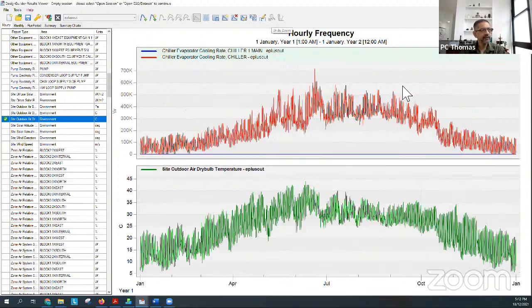So what I can do is take that 700 and split it into a 40-60 ratio. So about 250, 280 kilowatts and 420. So what I'll do is make both slightly bigger than that, make them 240 and 500. Okay, let's say 250 and 500 kilowatts. That'll give me what I want. So there's a reason for doing that.